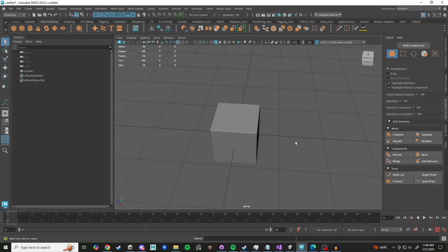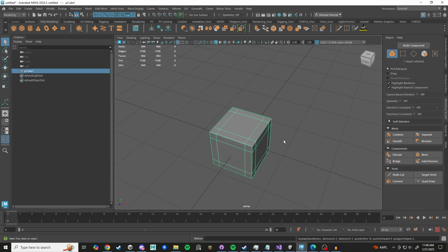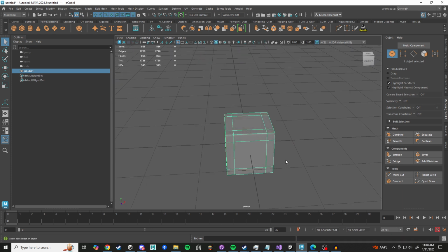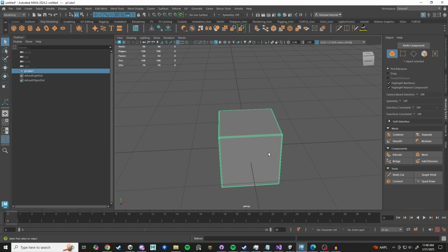So subdiv modeling is intended for shapes that you're going to apply extra subdivisions to using the Catmull-Clark sort of math behind it. So whenever you press 1 and 3, you can see that it's subdividing those and kind of smoothing them out with that smooth preview, right? That's kind of where you can go with subdiv modeling.